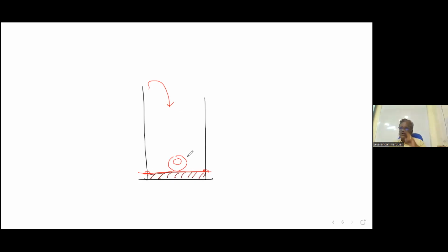Then what do we do? We again have options. One option is, if possible, we can trim the reinforcement plate. Second option is we can cut it and make a tombstone shape, weld with the shell to bottom. If both options are not possible, remove it and replace it, shift it to the upper side.